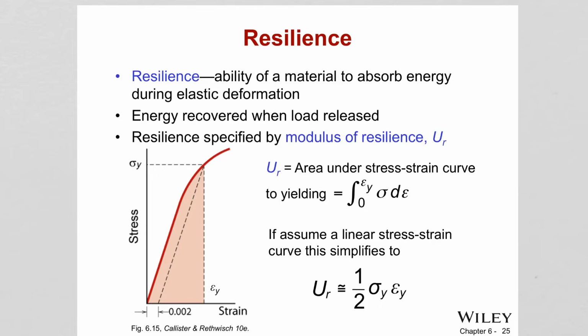So force times distance is work. Work is energy. Basically by stretching the material, you are storing energy inside those bonds, those springs in between the atoms, basically imaginary springs. That energy is recovered when we release the load.